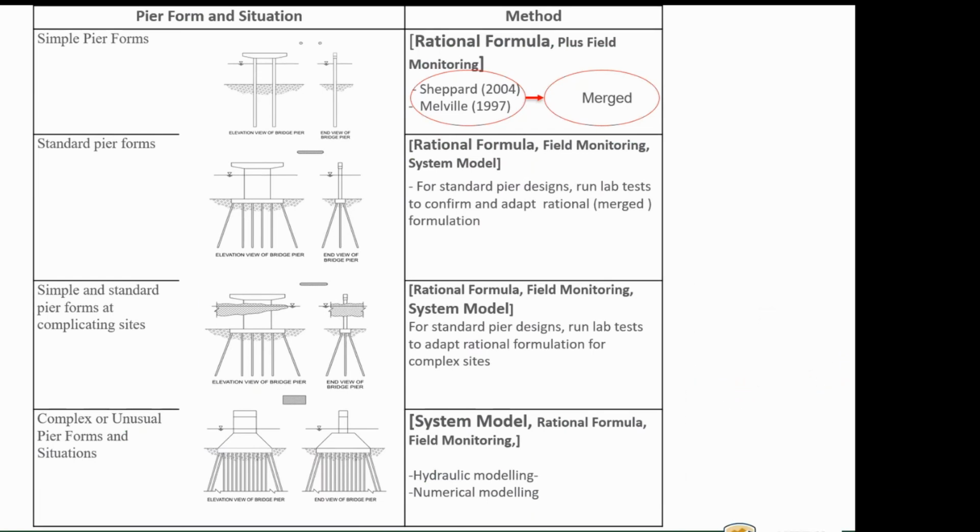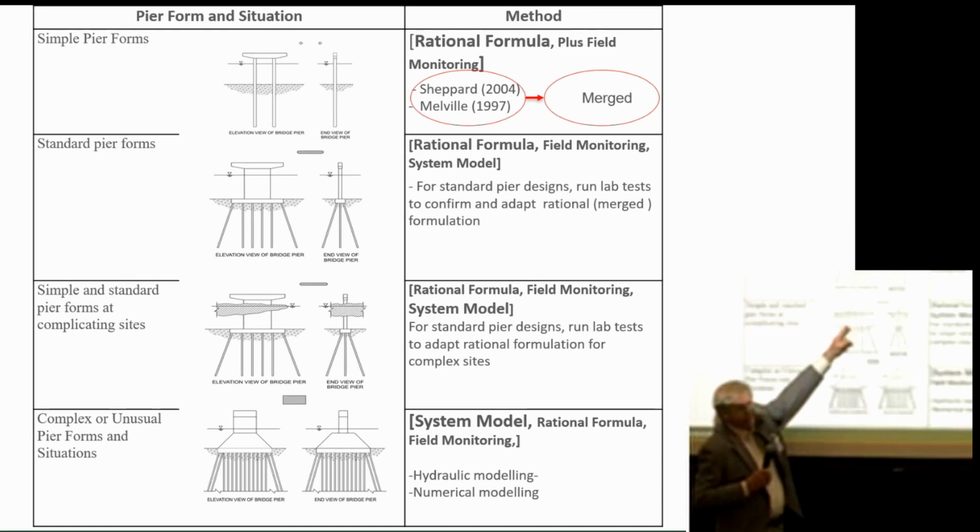And I'll show that bridges in Nebraska are built too low. Road bridges are; rail bridges are better. It's cheaper to build a lower bridge than a higher bridge, but you need to allow enough distance for accumulation, particularly of ice. Part of the challenge of climate change is that the frequency of these events diminishes, and so the designers of these bridges tend to neglect woody debris or ice or treat it as a nuisance. But in fact, there's not enough clearance given, certainly not in Nebraska, in my opinion, between the bridge deck and the water level. Woody debris increases the load on bridges, so a lot of bridges fail because the drag on the woody debris is transferred to the bridge.